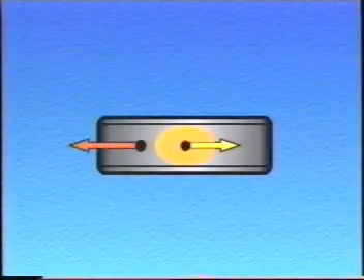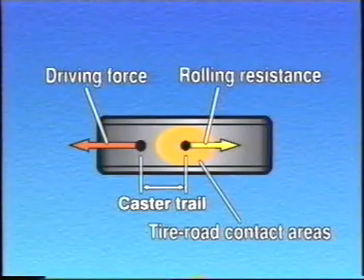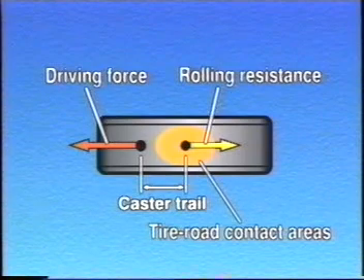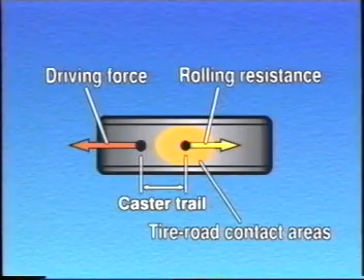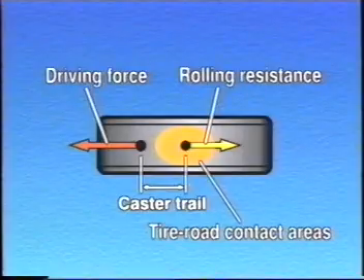This figure shows the composite force acting at the wheel-to-road contact area, represented by the circle. The tire friction at the center of the wheel-to-road contact area opposes the forward-acting force by the trail amount. This provides stability while driving straight.